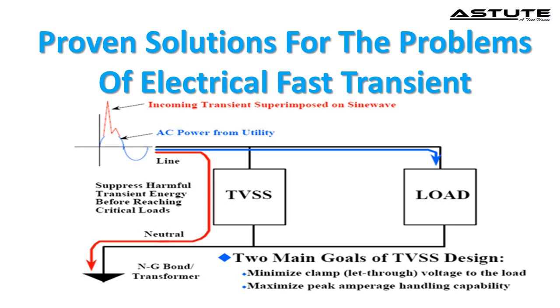Do not route filtered and unfiltered lines in a single cable bundle or close to each other. Keep the lines from noise generators such as relays and inductive loads away from sensitive lines such as low-level analog signals and communication lines such as I2C, SCL, SDA, and UART.